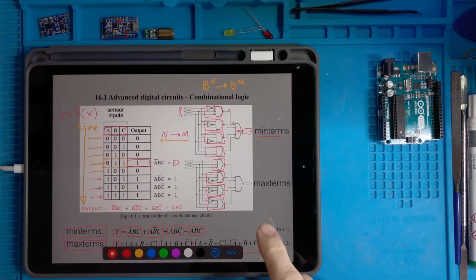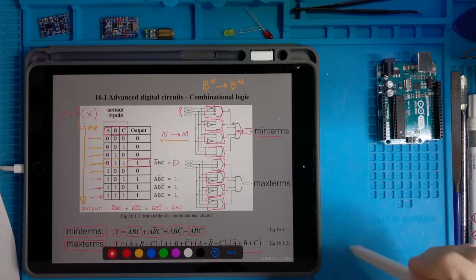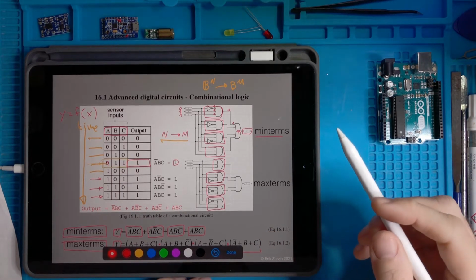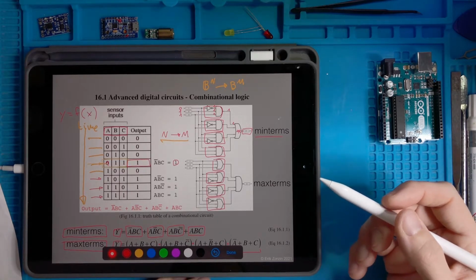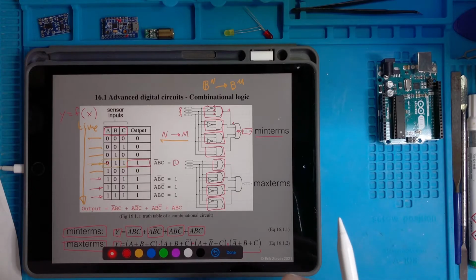So in the microchips, I mean silicon, there is this thing: the dominant components at the fundamental level, even inside the diodes and the transistors, are of two types, resistive and capacitive. So we don't have so many inductors. It means that the magnetic field in a microchip is very small. And this makes a dramatic change in what is called the propagation time for the signals.